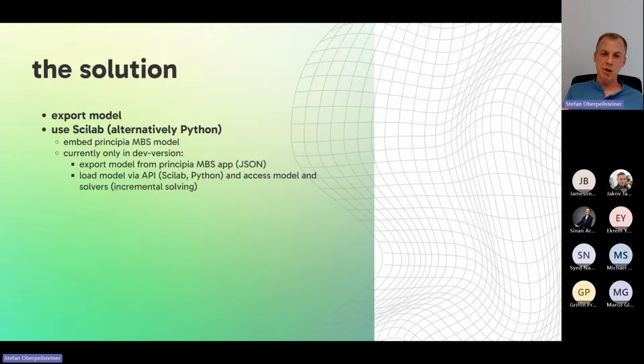The model there can not only be read out, but also used for incremental solving. That means you define a small time step size that is simulated, then you get all the information, the readings out of the model, do something with it, in this case, define the control law, and then compute new inputs for the model, and then simulate one incremental step again.